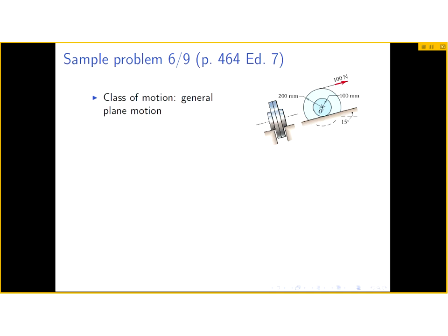It's difficult to solve the differential equation of motion, but it's not so difficult to calculate the kinetic energy and the potential energy at an initial and a final point in time, and then use the conservation laws or the work energy equations to solve for the unknowns that were asked.